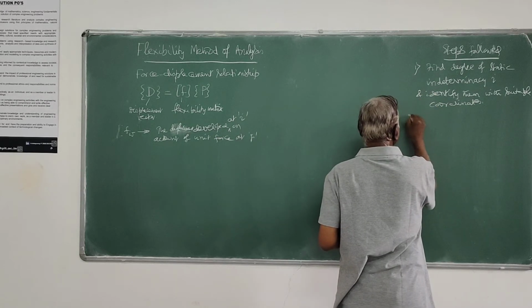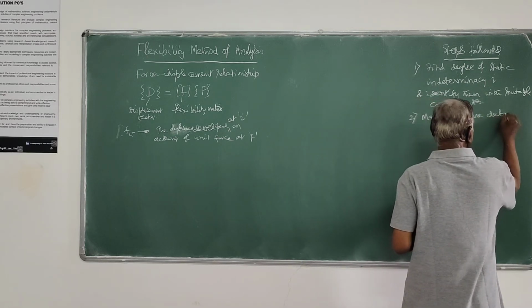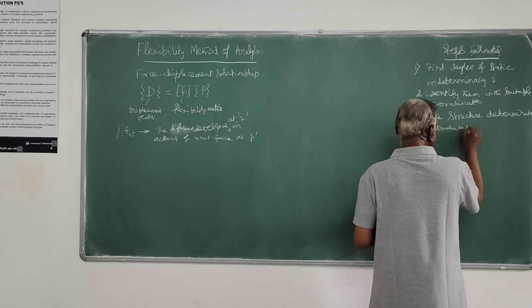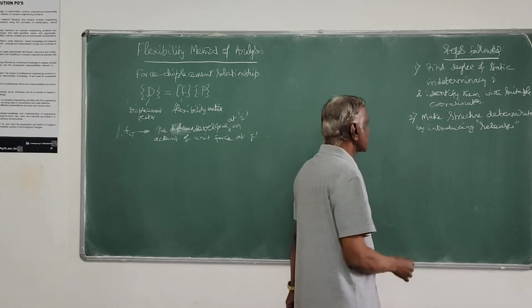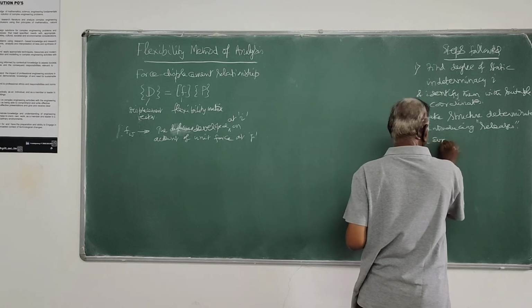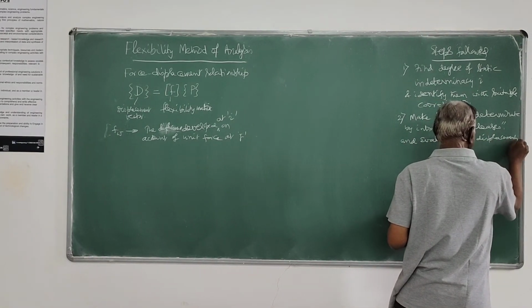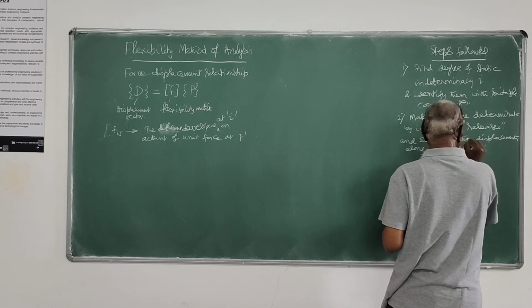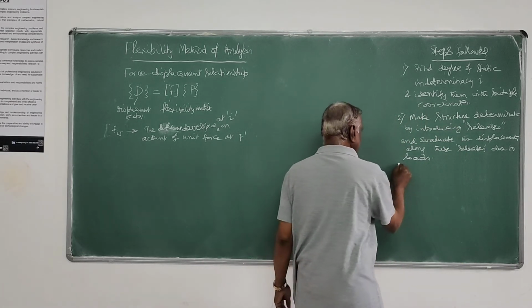So find the static indeterminacy, and second, make the structure determinate by introducing releases in the form of force at suitable points, then evaluate the displacements along these releases due to given loads.